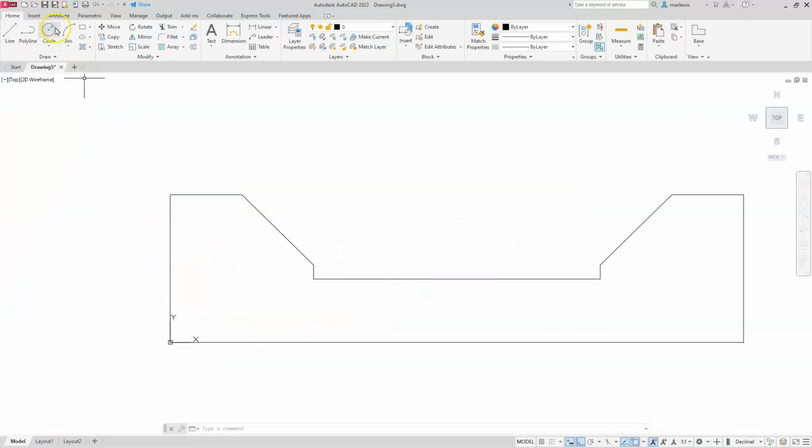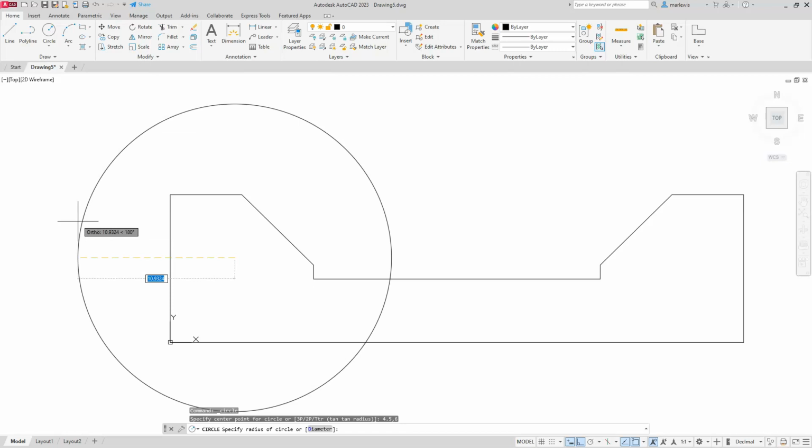Okay, so let's go ahead and use the circle command, and by default, it's set to my radius one here at the top. So circle, center radius. Now you don't have to select in the drop down. Remember that you can always just select the one that's at the top. That looks like the radius icon, so I don't have to select the drop down to go to that. I can select the top icon, and now it's asking me where do I want to place it. So in the drawing, the X component was sitting at 4.5, comma, and the Y component was sitting at 6 up, so 6. Once I hit enter, it will place the center of that circle, and I'll type in the radius in this case, which is 2.